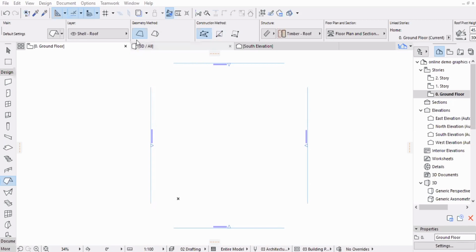So we are starting to draw a lean-to roof. Now, if you can imagine a lean-to roof, you can imagine that to be a piece of A4 size paper, and you want to make it look like an inclined plane. What would you have? You would have an edge of that paper, which you would keep stationed, right? And the other edge of the paper would be rotated about the edge that you have kept stationed. So the edge that you kept stationed is called a pivot line.